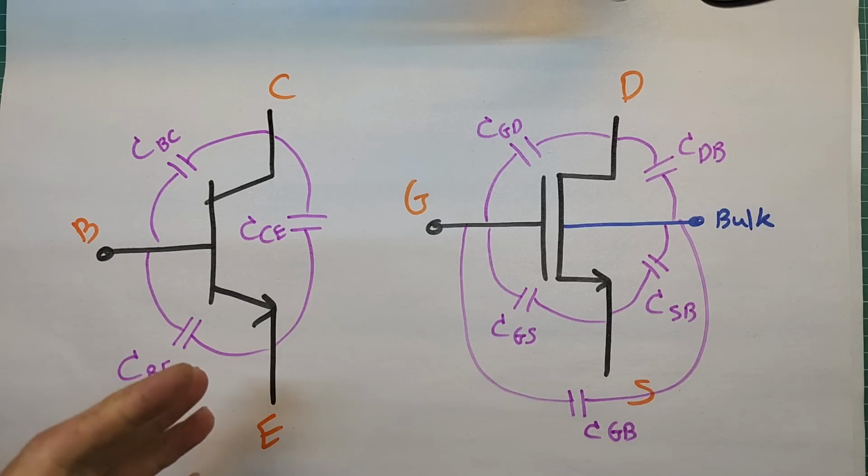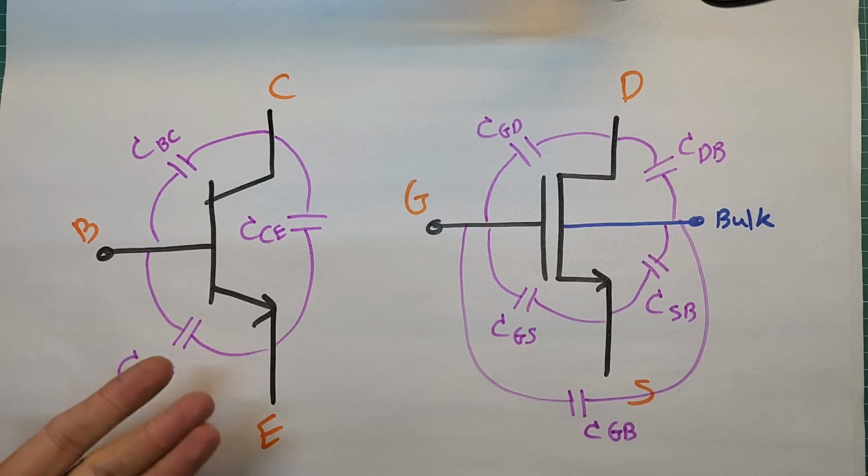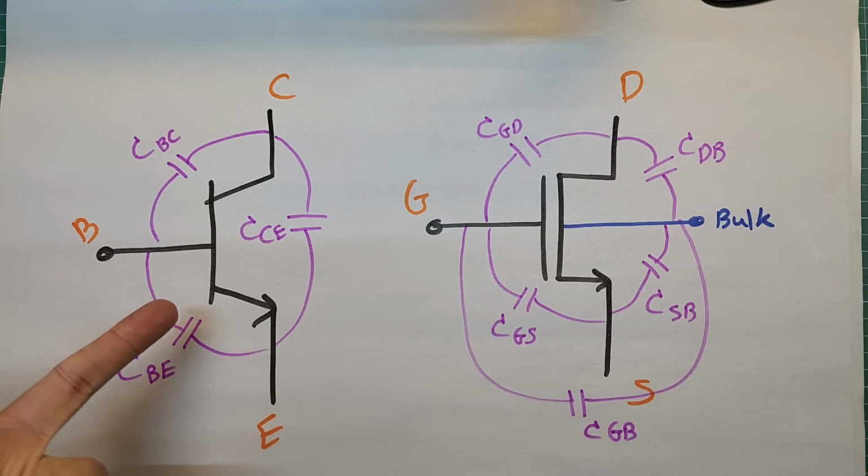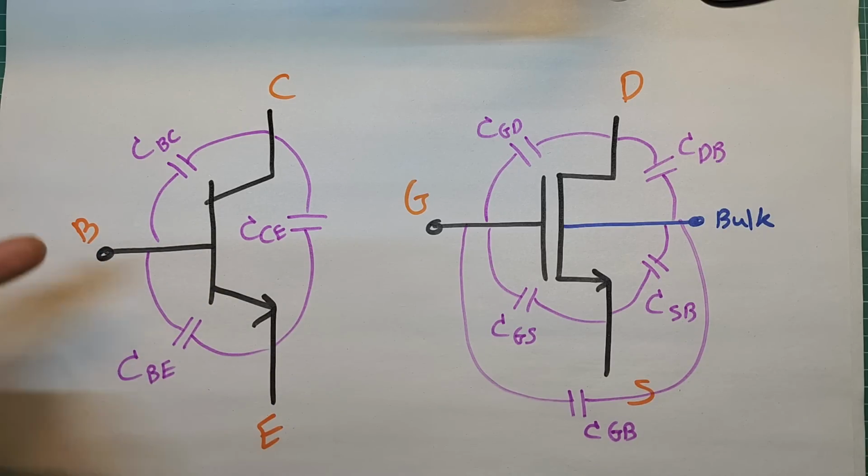On the other hand, when you stop applying voltage to the base emitter junction to turn the transistor off, the current flowing to the base will not stop immediately because there are some charges stored in these capacitors, and the current flowing to the base will continue until these capacitors are discharged. This process is time consuming as well.